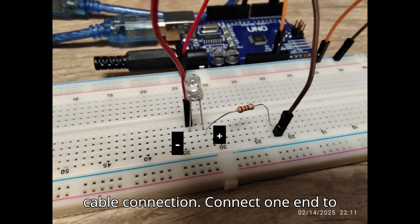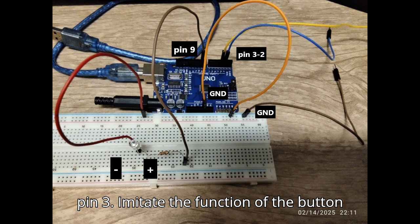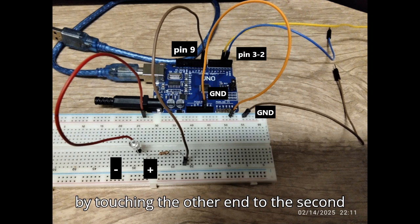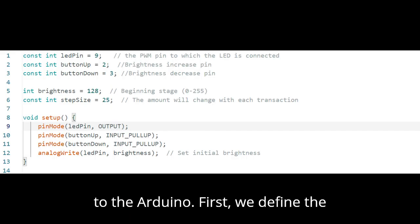Jumper cable connection. Connect one end to ground, and connect the other two ends, one to pin 2 and the other to pin 3. Imitate the function of the button by touching the other end to the second or third pin with your hand. Let's take a look at the code we uploaded to the Arduino.